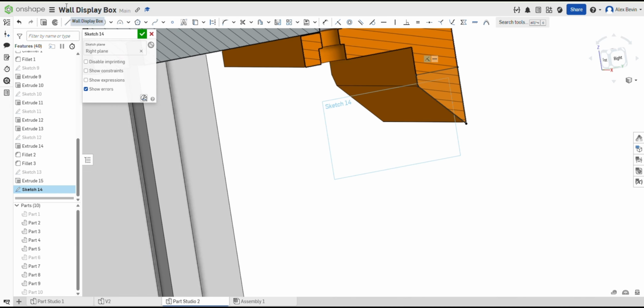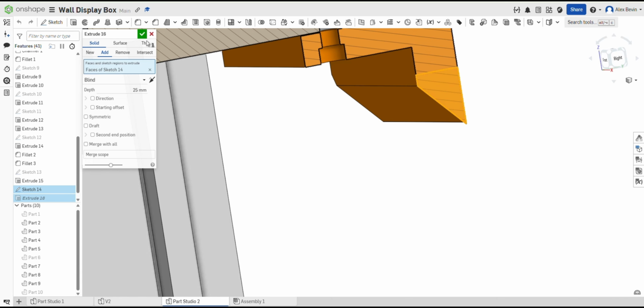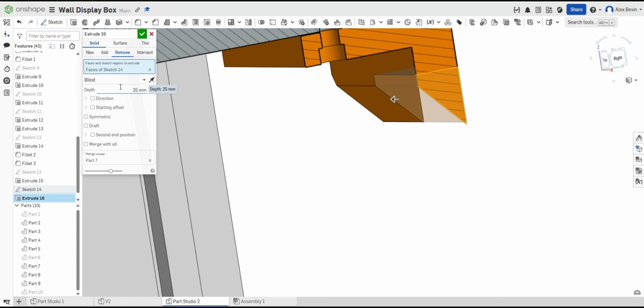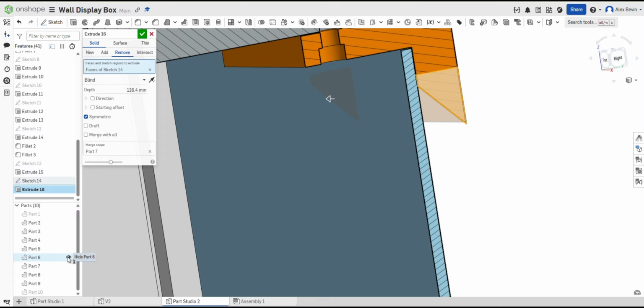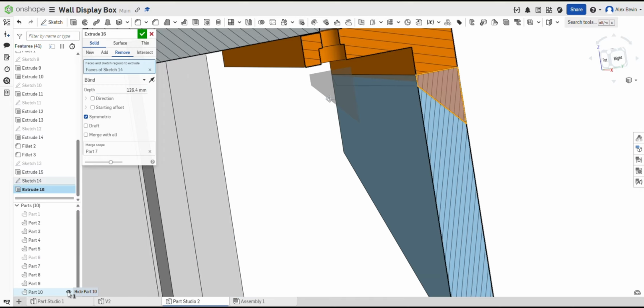Section A. Remove the clash. Triangle cutout. If I turn on a section view, you'll notice there's a clash between the top plate and the bottom cleat. That clash is normal at this stage, we just haven't cut the clearance yet. I'm going to use the right plane for this because it's the easiest way to see what's actually intersecting. Right-click the right plane. Section view. Then press N for normal.